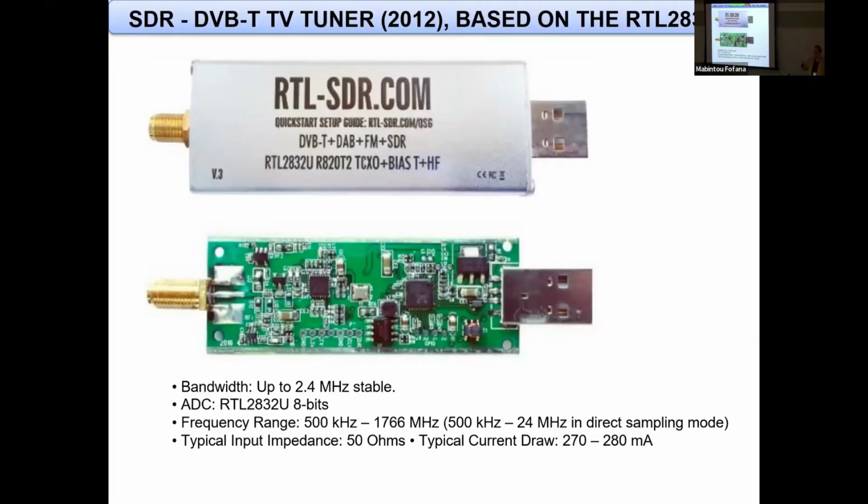What does it do? Yes, I'm sorry, what does that board do? I see an antenna RF on the left and I see USB on the right. Yeah, that's a good question, because what it's doing is directly taking an RF in. From what band? From how wide? From 20 megahertz to 700 megahertz. Cute. And this is $30? $30. How come it's only $30? Miracle of, this was originally designed for TVs. Oh, okay. So what comes in here is your RF. I even have a slide on that.